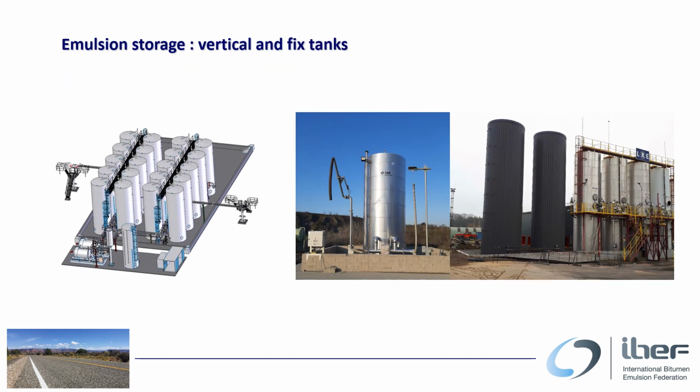For the storage of the emulsion, the vertical version is the best in order to avoid the skin at the surface of the liquid. This fixed configuration is mainly chosen in case of big volumes of production each year. For the storage of emulsion, carbon steel can be used, and stainless steel is selected in case of very aggressive emulsion with high acid content.